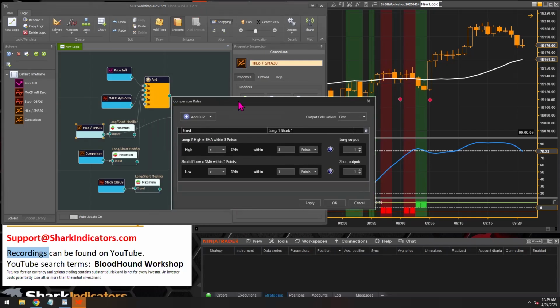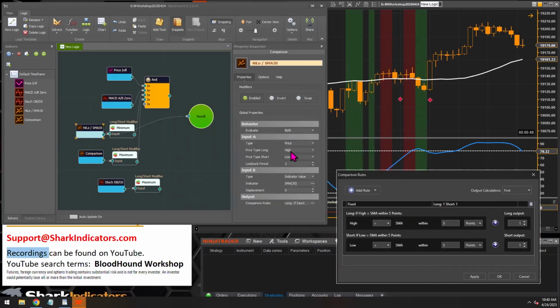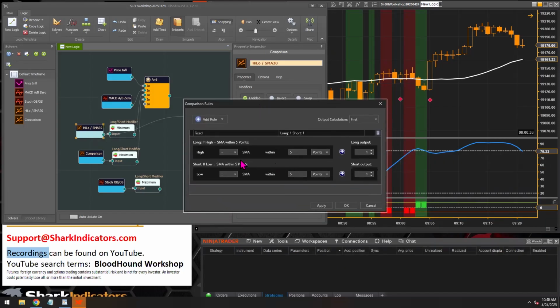You have to make sure you've got the right solver selected. It's an easy mistake to make. When you're moving solvers around, you might be left with the wrong solver selected. So be very mindful when you're editing your solvers, because it's easy to forget that you moved something and left it selected, even though you wanted to edit another solver.